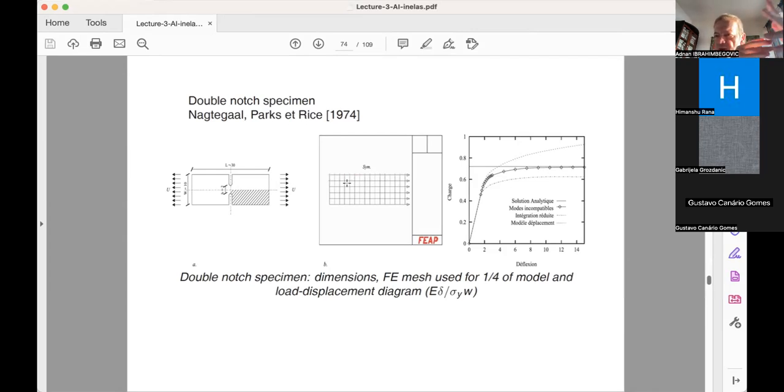So incompatible mode interpolation would have that, because incompatible modes allow this element to kind of breathe, to accommodate this. Whereas with isoparametric elements, we already studied that if you have this locked, this locked, this locked, and then you have incompressibility, this node cannot move. So now this is quasi-incompressible, so it barely moves, but not much. So you really kind of lock, and you cannot do it there.